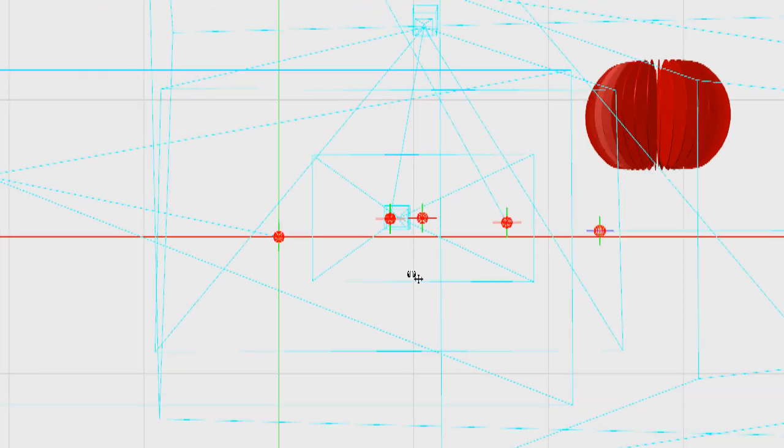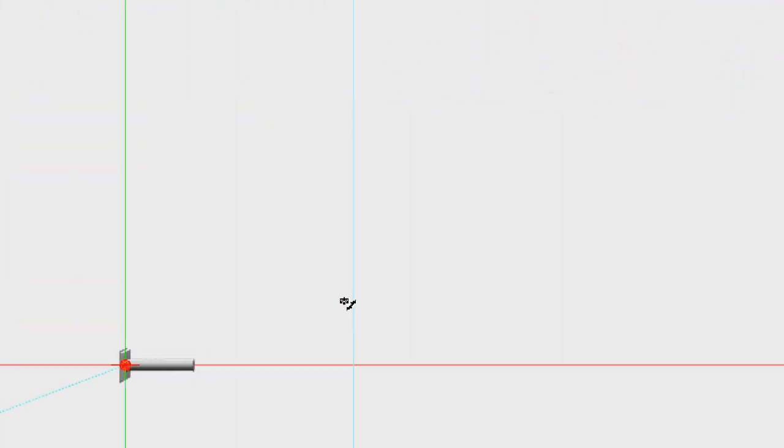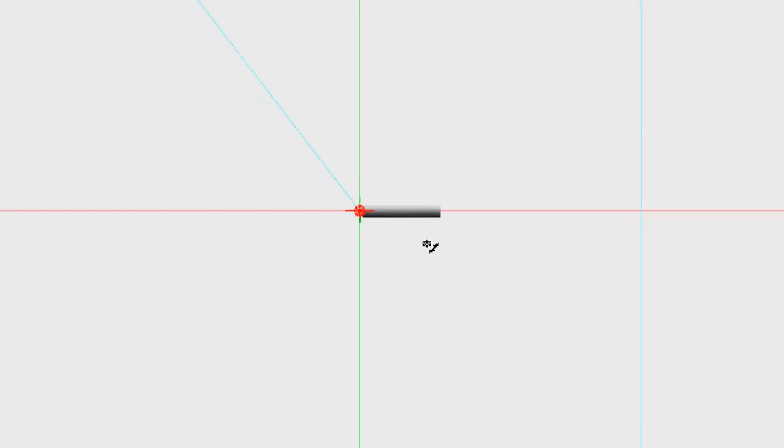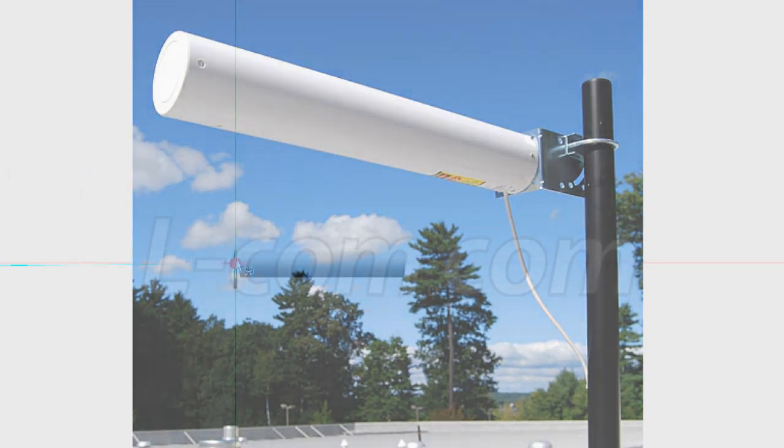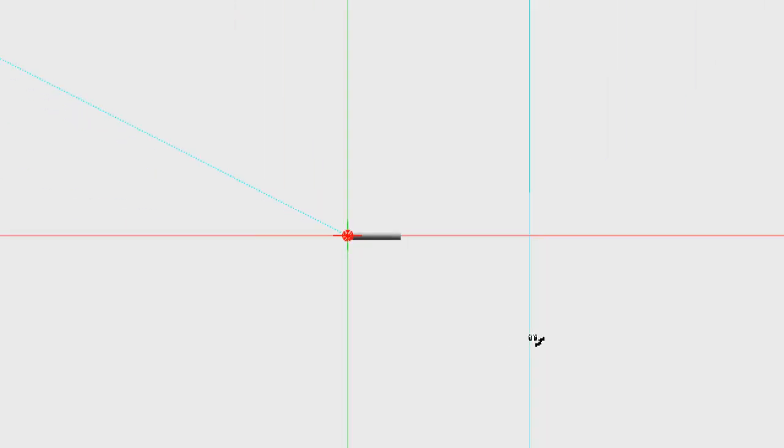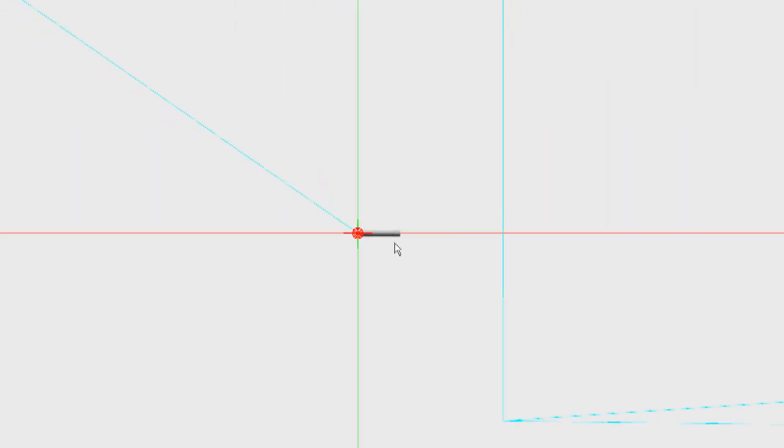Quite a popular high gain antenna. I mean, it's not much difference between a patch antenna and a Yagi, but we're going to look at the Yagi, which is, we'll turn off the Diversity antenna. Yagi is like a tube, yeah. And if you compare that to your rubber ducky antenna, these can be up to 2 meters long if you get extremely high gain. But we're going to base this on the 15 decibel Yagi antenna. So remember, the diversity was 11, the circular was 8, and the rubber ducky is 2. So this is your Yagi, which is 15 decibel, which is about half a meter long.